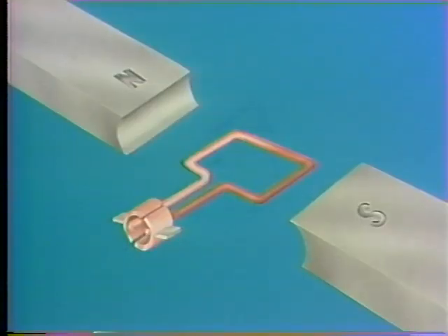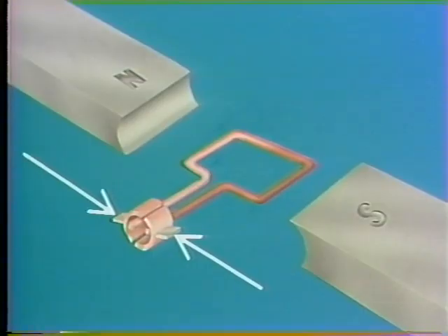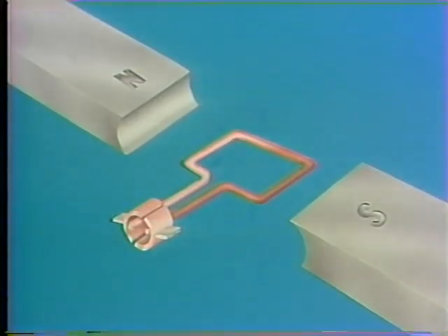These parts here will do the job. These are commutator segments, and these are brushes. These commutator segments actually come from a copper ring that was cut in half. We attach one segment to each end of the conductor, so they'll turn with it. We're going to use the brushes as the link between the power supply and the segments on the conductor. These are made of a carbon material that's similar to the lead in a pencil. These brushes don't move. The commutator segments slide against them as they turn.